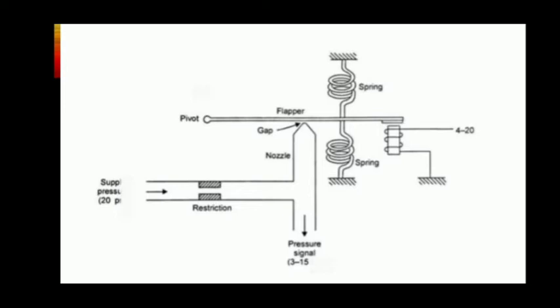In electro-pneumatic controls, mainly 3 important steps are involved. Signal input devices, signal generation such as switches and contactors, various types of contact and proximity sensors. Signal processing, use of a combination of contactors or relays or using programmable logic controllers. Signal outputs obtained after processing are used for activation of solenoids, indicators or audible alarms.